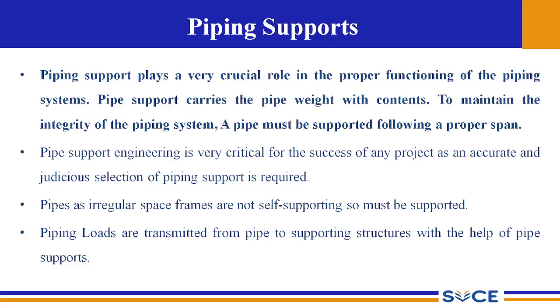The piping loads will be transmitted from the pipe to the supporting structures with the help of the pipe supports. So we have to calculate the load of the pipe with its contents, and those piping loads need to be transmitted to the supporting structures with the help of the pipe supports.